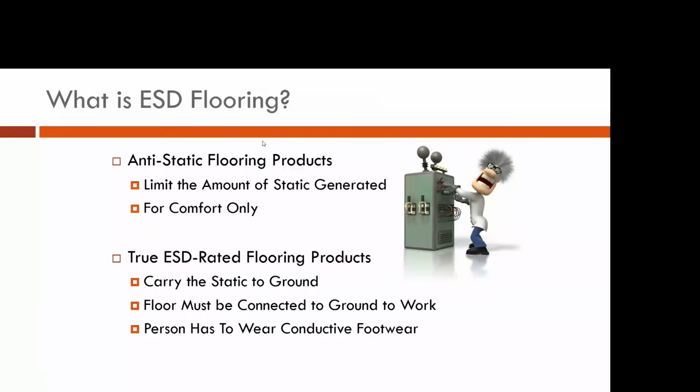And one thing to note is that the person has to wear conductive footwear, whether it be ESD shoes, heel grounders, sole grounders. Otherwise, they're not connected to ground. So there are no ESD floors available where you don't have to use ESD shoes or a heel grounder or an ESD foot strap, because otherwise you would not be able to be connected to ground.